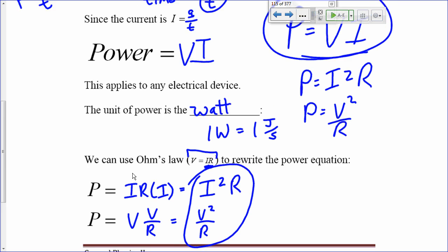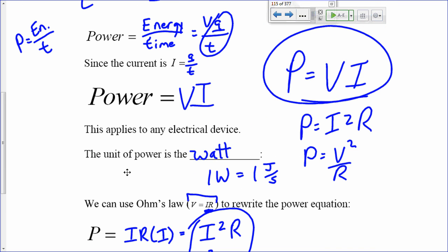All right. Electricians often use this when you're building a house. You have to estimate how much current is going to be drawn onto a particular circuit so that that circuit's not overloaded. And you can take your power ratings from your appliances or whatever it is that you're using and figure out how much total current is drawn on a particular circuit. We'll look at that in the next chapter. It's fairly interesting. You ever seen this? P is VI?